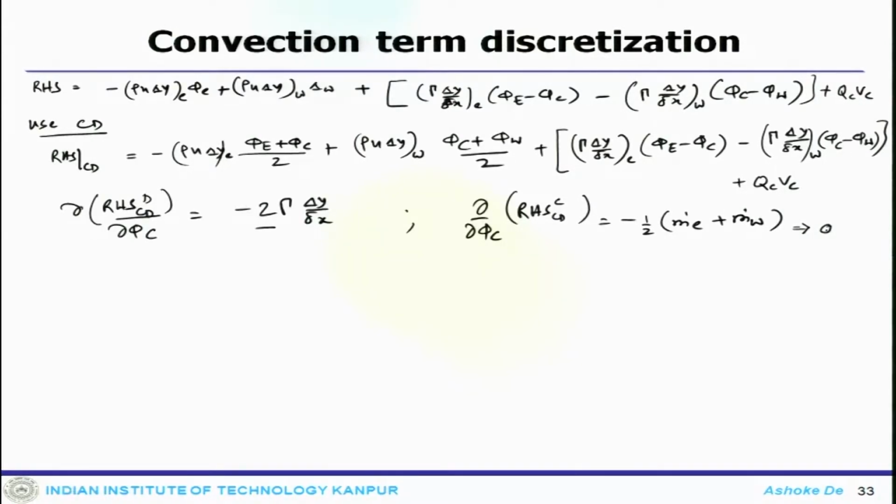For unsteady situations, its value will be positive for decelerating flow. Now, in general flow, such regions will act as sources and can easily lead to some sort of numerical failure when the Peclet number is large.